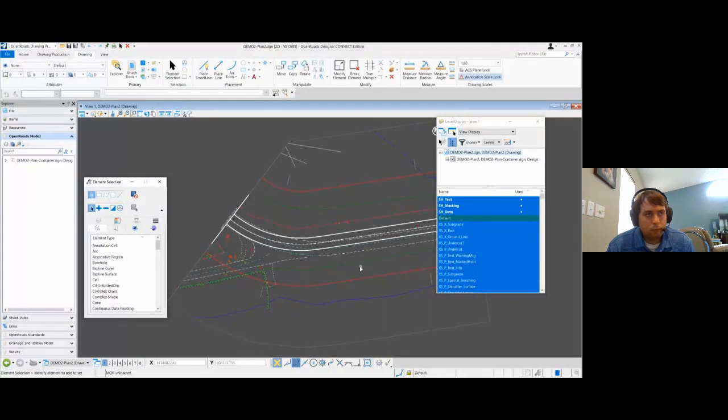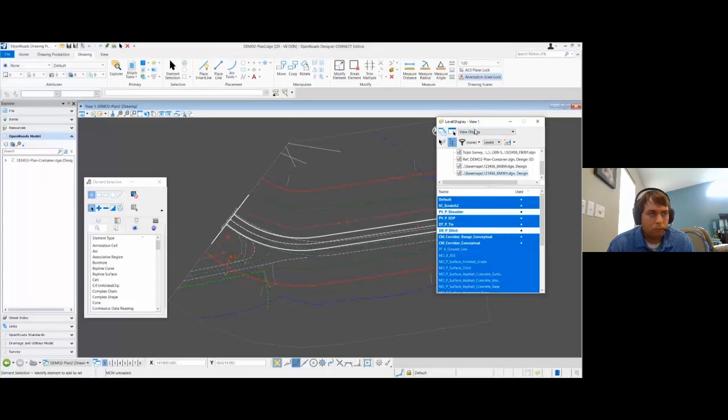Okay, so if we take a look here, you'll see that it didn't really do much. We had the ditch off before, if you guys remember that, as well as the shoulder, but I turned off the edge pavement globally, but it's still on here. So the variable's off, right? And I also turned off these levels, and they're still on, right? Which if you look back in the video, you'll see that Scratch 2 was off before I ran that. So you see nothing really changed here, right?